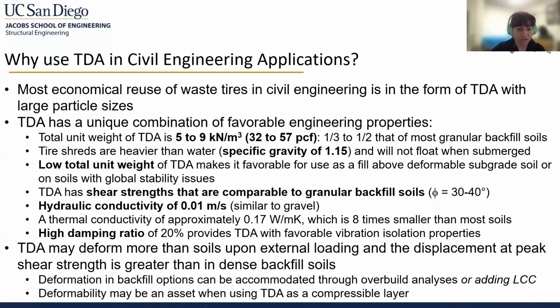TDA, it is also to note, may deform more than soils upon external loading, and the displacement at peak shear strength is greater than in dense backfill soils. Additionally, deformation in backfill options can be accommodated through overbuild analysis or adding lightweight cellular concrete, and deformability may be an asset when using TDA as a compressible layer specifically.